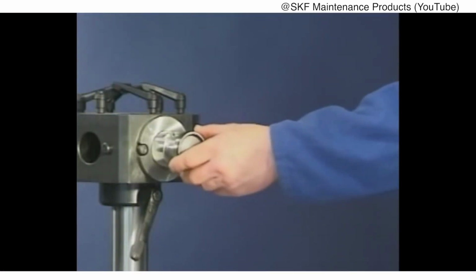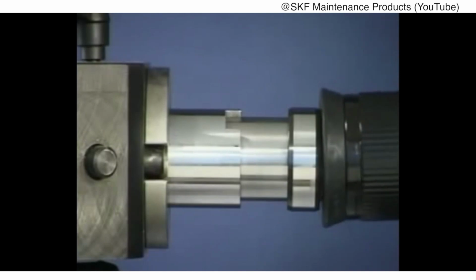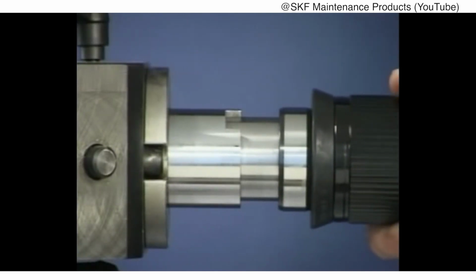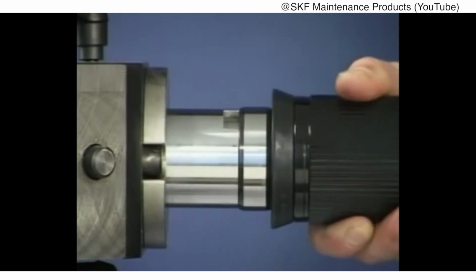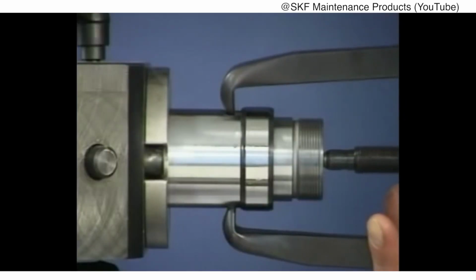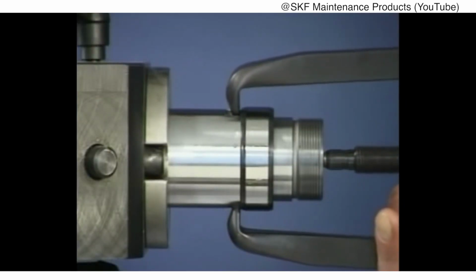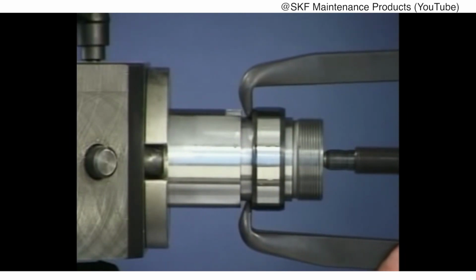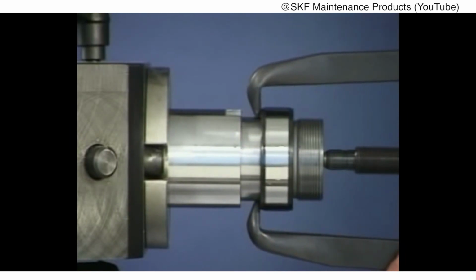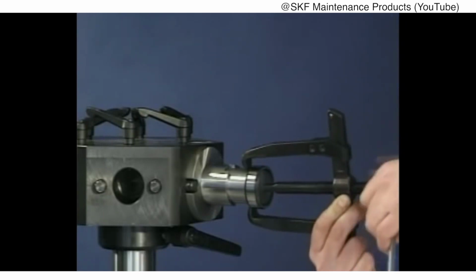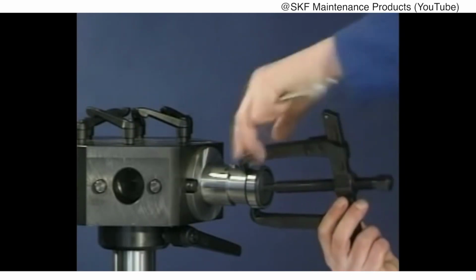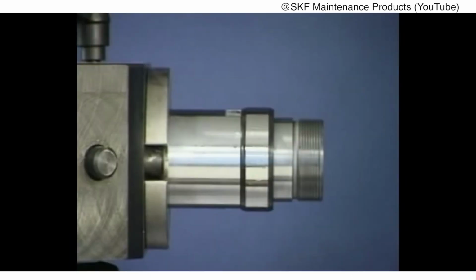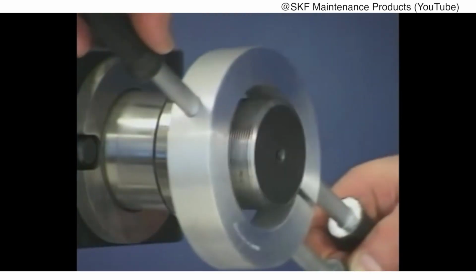When mounting bearings onto shafts, care should be taken not to misalign the spheres or cylindrical rollers within, as this can damage the bearing, decreasing performance and lifespan. To mate bearings to shafts, special tools which apply force to a bearing's raceway are typically used. When designing machines which require bearings, engineers will often create shafts with stepped profiles to ease bearing assembly.